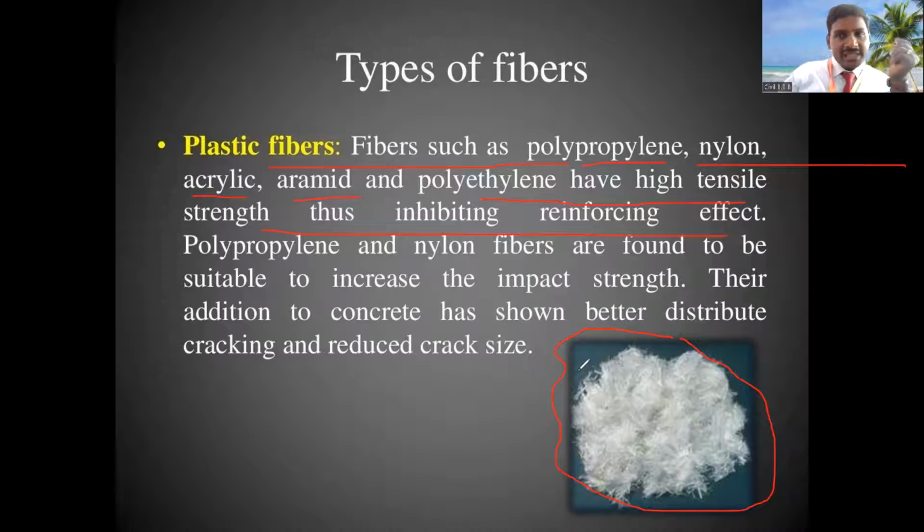If we add this plastic fiber into the concrete, your tensile strength will increase. The concrete will not fail at an early age. If we add this particular fiber, the strength of concrete or elongation will increase, and ductility will increase.